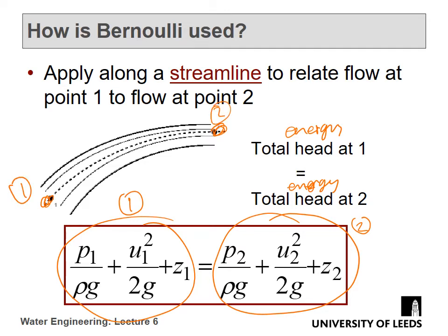Okay. What this allows us to do is to relate pressures at different points in the fluid, whereas remember the continuity equation allowed us to relate velocities at different points in the fluid, and the two together, the Bernoulli equation and continuity equation, allow us to solve many features of flows, in fact most of the flows that we'll come across.